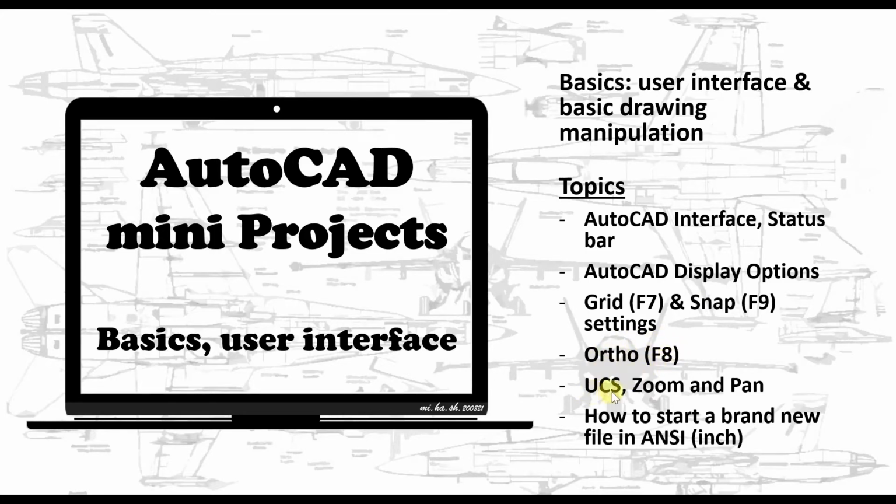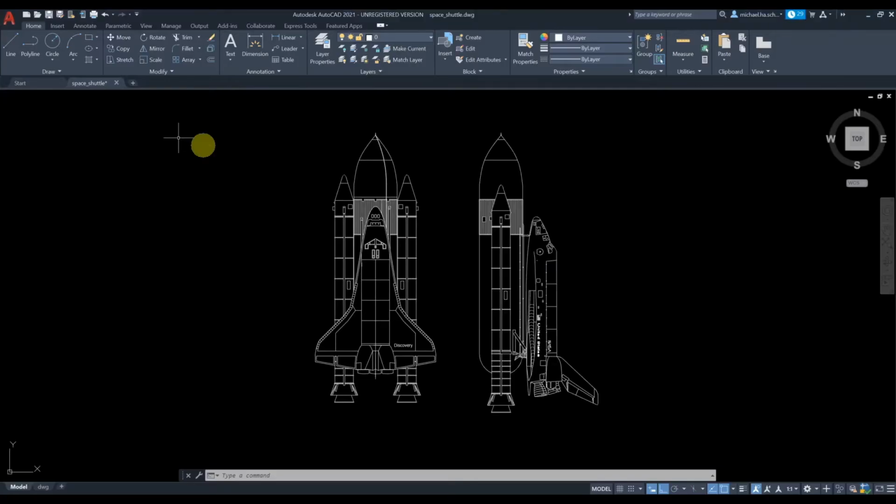So what is the universal coordinate system? And within that, we're going to talk about origin. Every space in an AutoCAD file has an origin, meaning the 0, 0, 0 point, where XYZ is 0. How to zoom and pan, and how to start a brand new file. And we're going to use a drawing template, DWT file, that comes when you install AutoCAD. So it comes standard. Okay, so let's go ahead to AutoCAD.